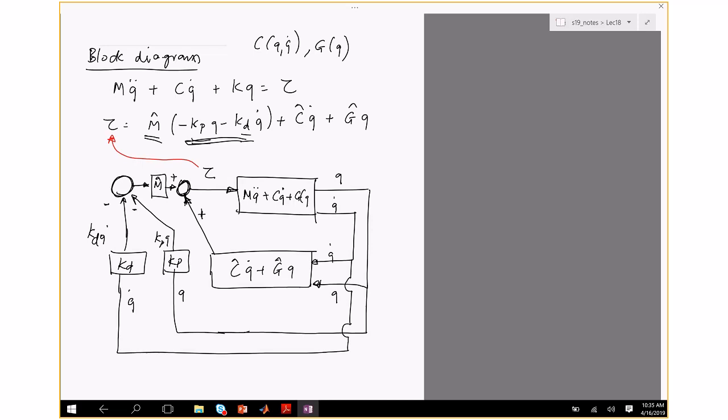So what this controller does is it actually tries to control the system to go back to zero, just like the spring mass damper. Most times we are not interested in going to zero. A manipulator has to track a trajectory. So we talked about trajectory generation. Given a start and a goal, we have the minimum trajectory that starts with zero velocity, zero acceleration, and goes to zero velocity, zero acceleration, at two different endpoints. We drew this time trajectory based on fitting a polynomial. So that's the trajectory we want to track. Typically we don't want to go to zero, but we want to be able to track the trajectory.